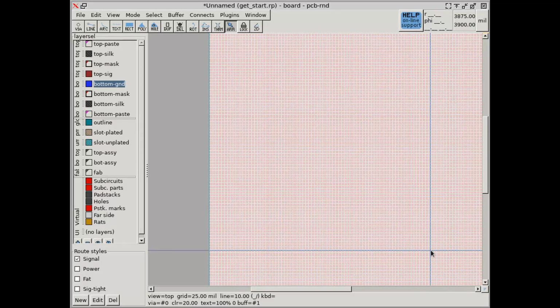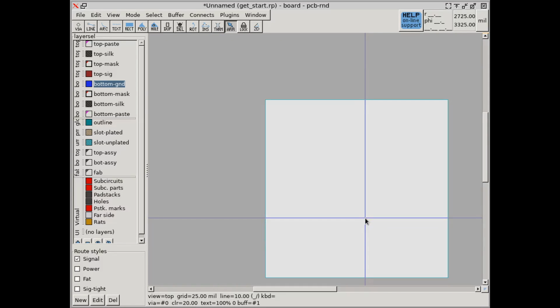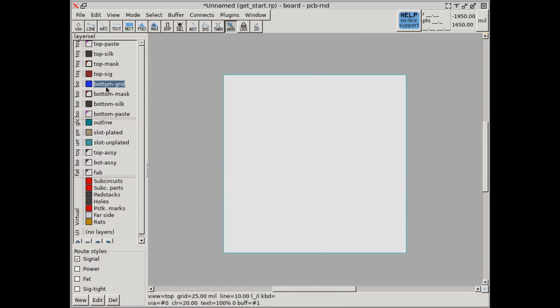Besides the layer stack-up, another important aspect is sizes. Trace thicknesses, minimum clearance, via hole size. Normally this is the best time in the workflow to set those up. For this tutorial video we are going to skip that. Defaults are good for both home etching and fabbing. Changing sizes will be covered in a subsequent video.